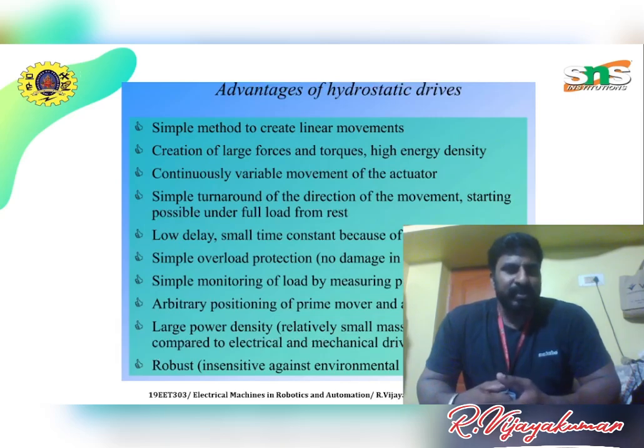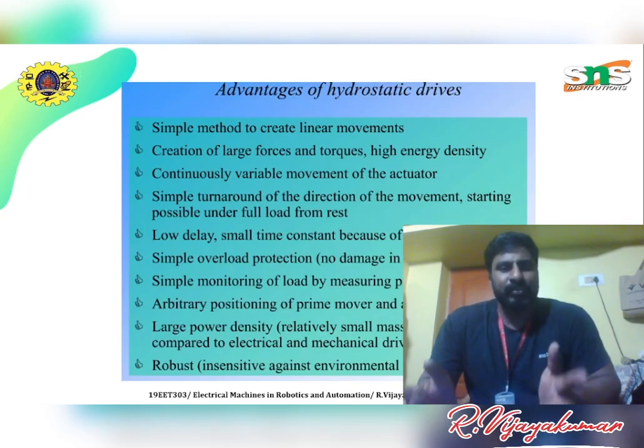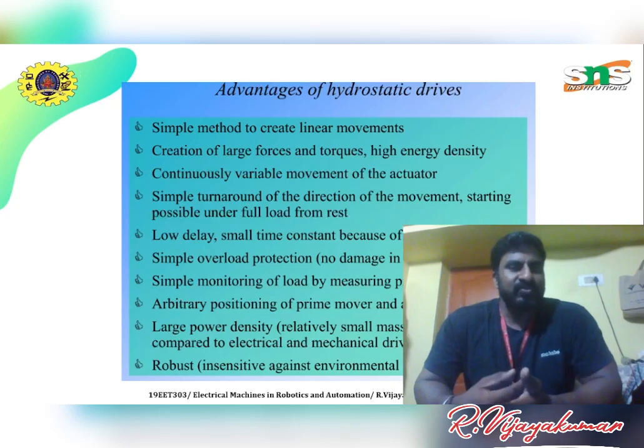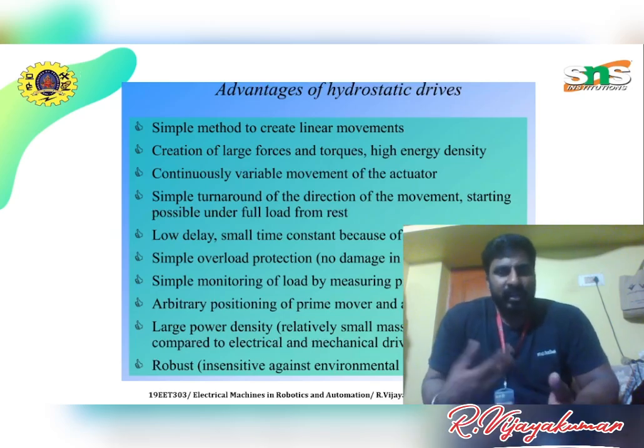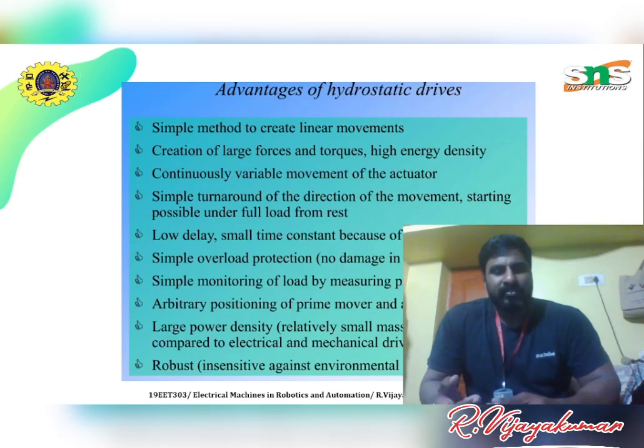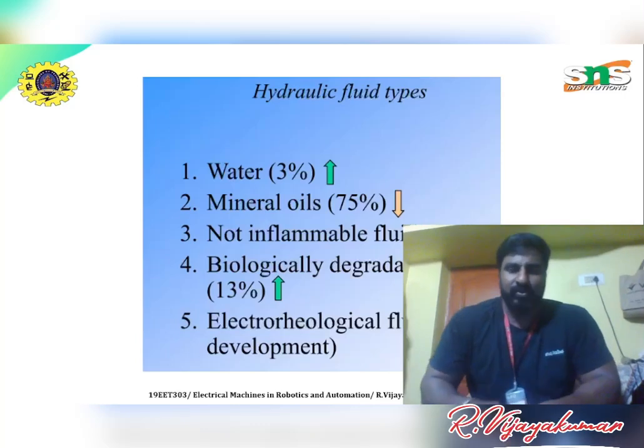Advantages of hydrostatic systems: a simple method to create linear movement, creation of large forces and torques, high energy density, and continuously variable movement of the actuators. Simple reversal of the direction of movement, and starting possible under full load from rest. Low delay and small time constant because of low inertia, simple overload protection, and simple monitoring of load by measuring pressure. Arbitrary positioning of prime mover and actuators, large power density, and also robustness.